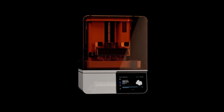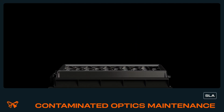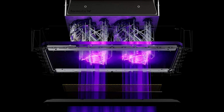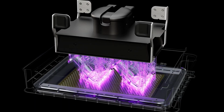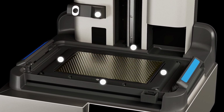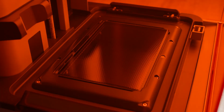Any contamination, dust, or debris on the printer's optical surfaces can cause the UV light that cures the resin to diffuse or weaken, resulting in a print failure. Contamination is most likely to occur on an exposed optical surface in the printer. In Form 4 and Form 4L generation printers, the optical surface most likely to be contaminated is the release texture, which sits atop the light processing unit, or LPU, and backlight unit.